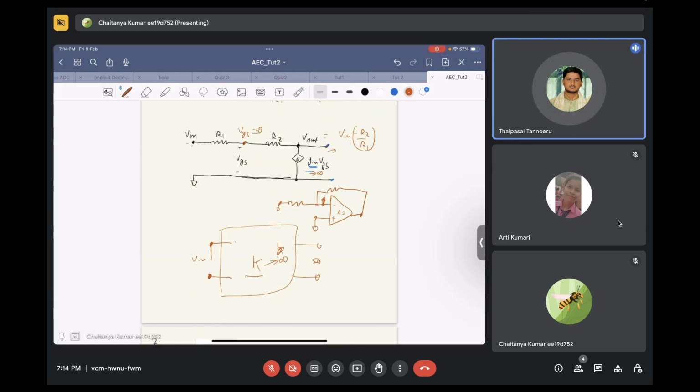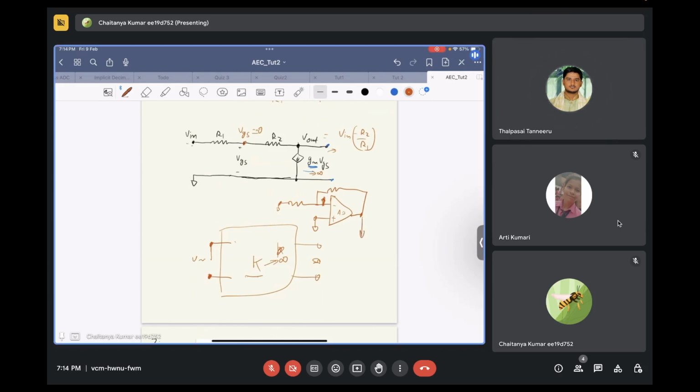Downwards, sir, because of the sign. Downwards, correct. Now, if the voltage tries to go downwards, the output will go downwards. If this output is going downwards, with the resistor divider between these two resistances, this will again go downwards. So even if this point tries to go upward, the negative feedback will make sure that it again comes back to the original position. Do you understand this? Yes, sir. Perfect.